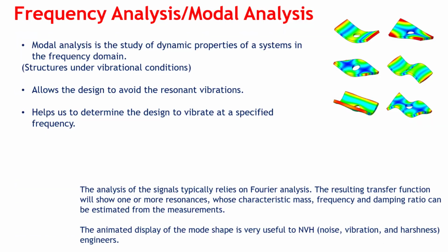So when it comes to this analysis, what exactly is this and why is it needed? This particular modal analysis is basically the study of the dynamic properties in the frequency domain. Let's say if you're going to deal with structures in vibrational conditions, we're going to deal with this analysis.